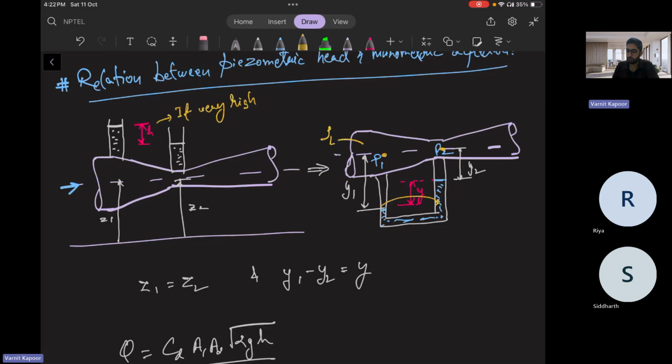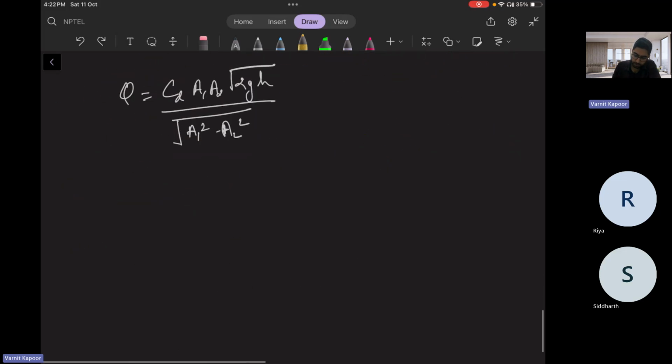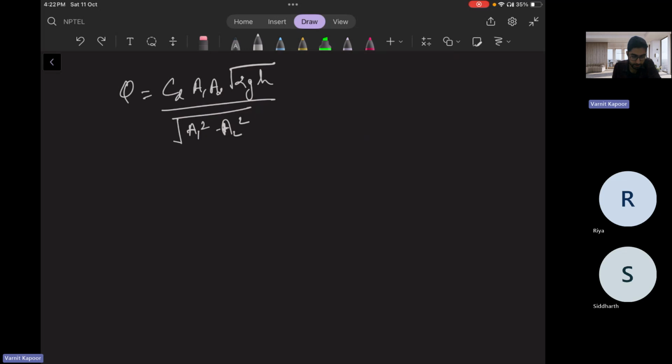Then you go above, so that is rho L g y with a minus, because you are going above, so pressure will be decreasing. Then again it is equal to pressure P2. So let us write the expression: P1 plus rho L g y1, then you jump it, you go above, fluid is same, rho L g y2 is equal to your pressure P2.